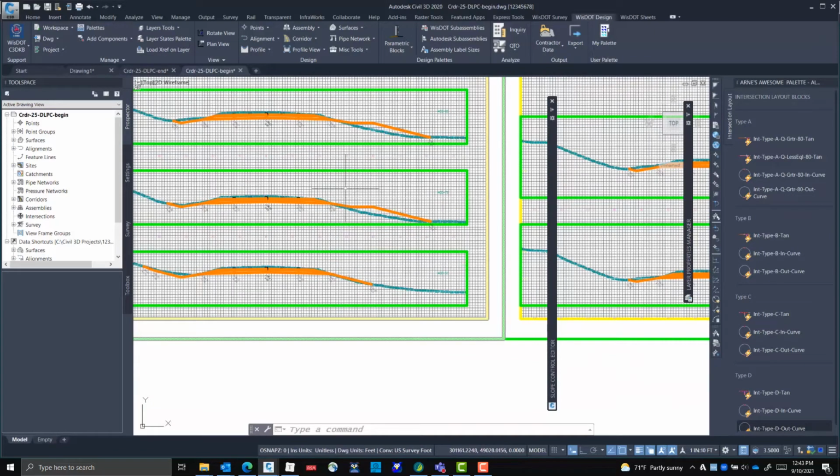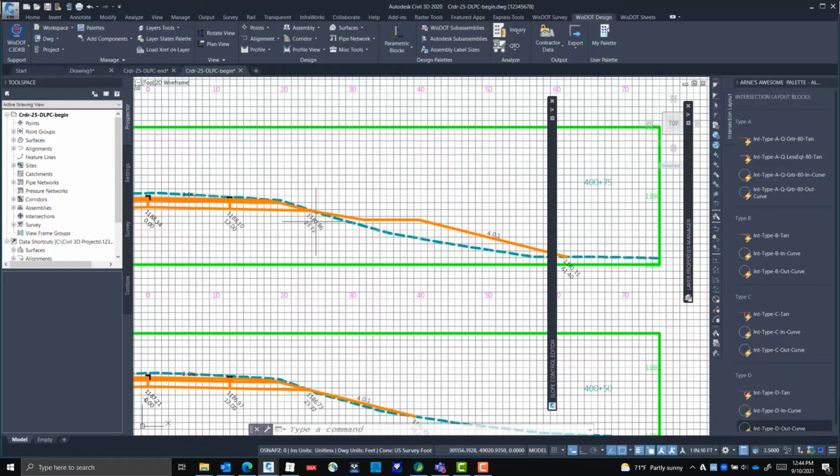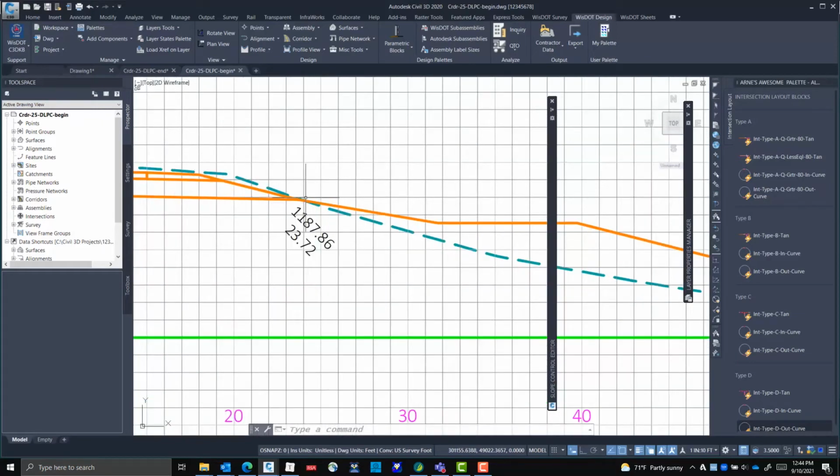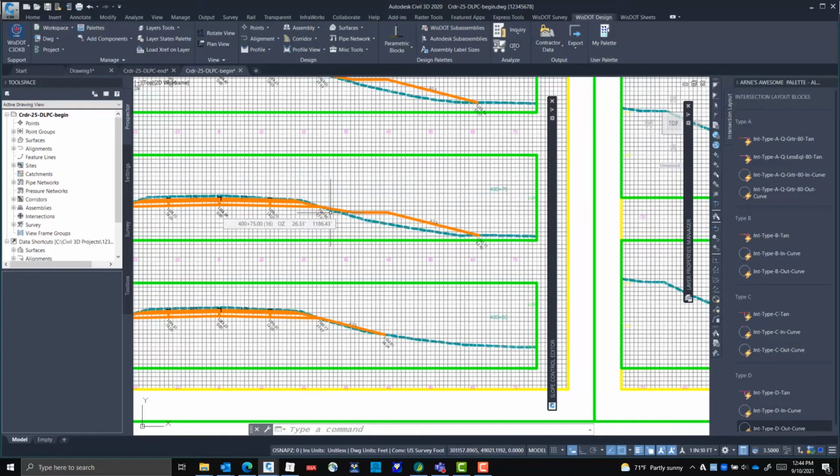Now we've got a little weirdness happening here. Well, what's happening here, which can be kind of common for daylighting links, is this is just underneath the existing ground. Okay. So the subassembly logic, which is pretty common in daylighting sub, says, oh, I'm underground. I must go up to go find the ground.